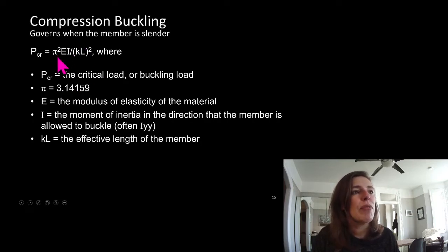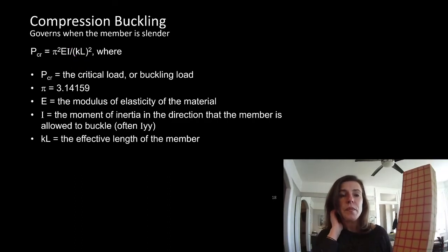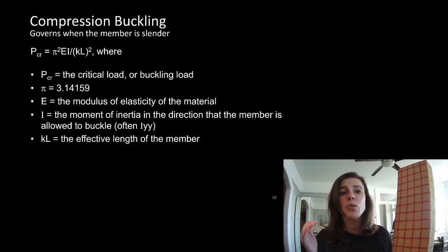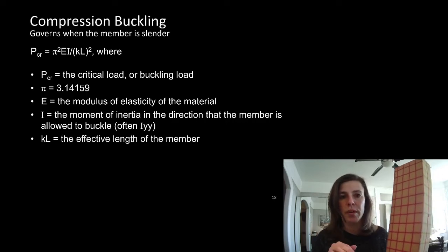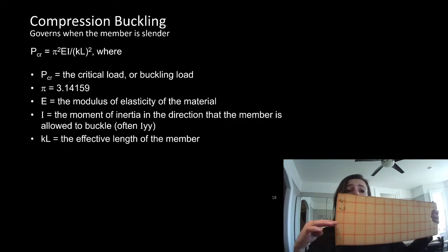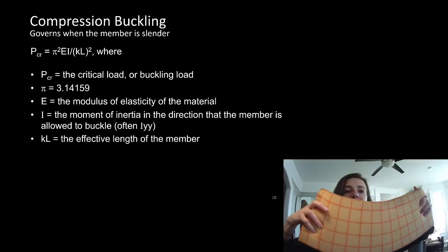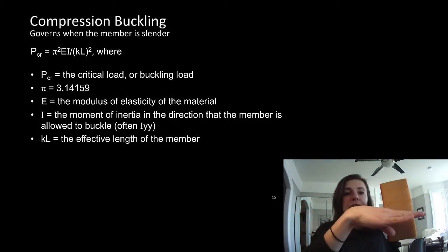Now look, we have pi, that's easy. EI. Well, E, we know, is all about the stiffness of our material, and for steel, it's 200,000 MPa. So we know both of these two things. I. Now this is where I said knowing what direction your thing is moving is important. Last week, when we were talking about bending, we were talking about things bending about this axis, like this. So that was our x-axis.